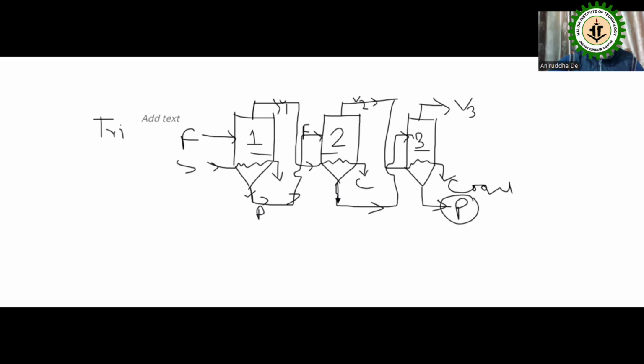Generally in large industries, food processing industries, triple falling film evaporators are used. Why? Because in a single effect evaporator, the desired consistency is not achieved. Suppose you want to go from 15 degree Brix, as I have discussed, to 60 degree Brix. In one effect we cannot achieve it. If we want to achieve it in a single effect, you have to recirculate continuously so that you reach 60 degree Brix.